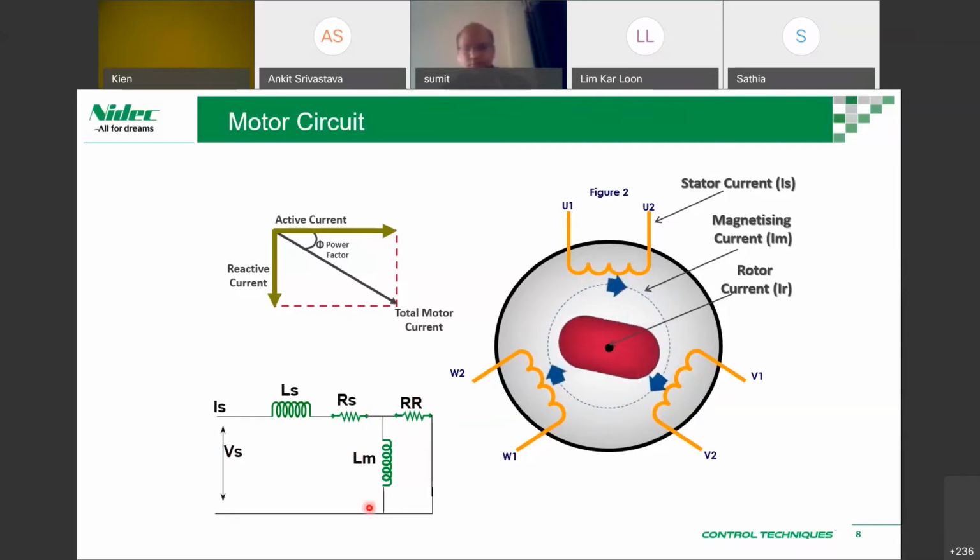So in critical applications, when we start commissioning, we try to understand these values by doing an auto tune. The drives will send out signals. They'll kind of do an experiment on the motor that they are connected to, and then take out these readings, and they keep these values to make sure they can control the motor to its optimal position.